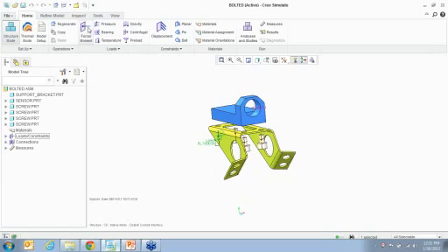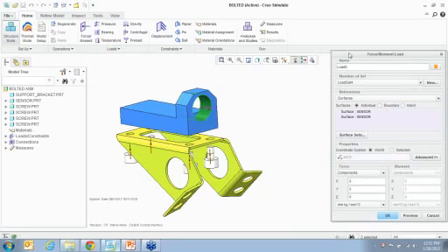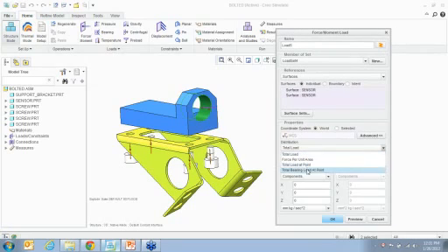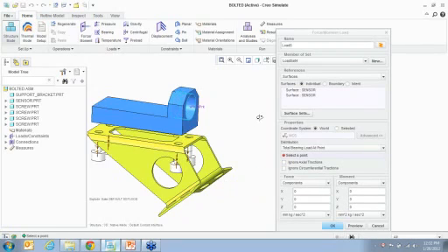Now I also want to go ahead and put a force load on this surface. Here a new enhancement would be total bearing load at a point. So I say total bearing load at a point. I'm going to pick a point right here and say it's acting in the Y direction at 1,100 newtons.